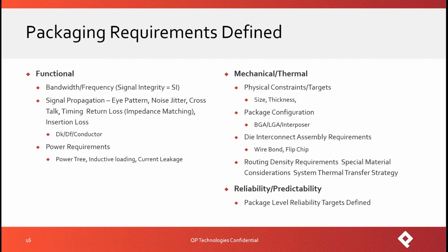They're all open cavity or can be made open cavity, so they all would have the ability for sensor interaction. We've done some BGA, and we've done some ceramic, and I think we did a few QFPs some time ago. Generally, when you're talking about a CMOS camera application, you're very cost sensitive, so a custom plastic probably is your best bet.